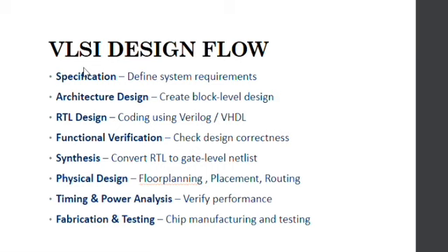Next stage is RTL design. RTL design is the stage where the chip's behavior is written using hardware description languages like Verilog or VHDL. It explains how data moves between registers and how the circuit works on each clock cycle.